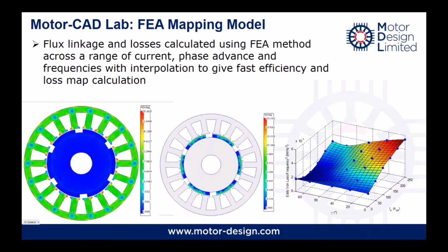It works by initially building a model based on the finite element. So it sweeps the performance of the machine through a range of different current magnitudes, phase advance angles and frequencies, and builds an equivalent model of the machine based on the finite element. That equivalent model is then used with a control strategy to calculate performance across the full operating range.